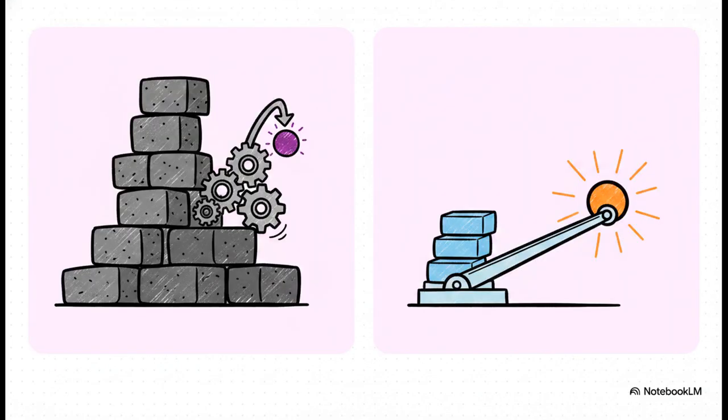Continuing to slide 19, when we do a mathematical comparison of these two power electronic giants, an incredible advantage emerges. To achieve the exact same level of power transfer enhancement on a given line, the SSSC actually requires a significantly lower megavolt ampere, or MVA, rating than the STATCOM. Why? Because the SSSC operates directly on the series impedance, rather than just supporting the voltage via shunt current. It's a vastly more efficient use of silicon and capital for the specific goal of pushing more active power.